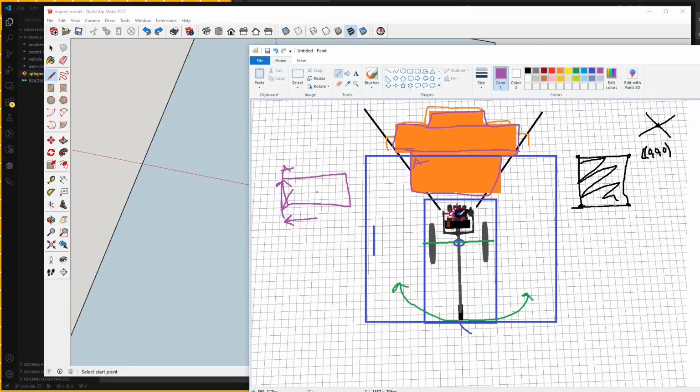And then with the IMU, if you say go forward 10 inches, which right now is assumed, there's no feedback yet with the IMU, but that will be added because I noticed even if I dial in the servos, it still slips somehow. So the 45 degrees is not perfect. But yeah, we'll start building a map from the scans, and so if it scans this, it'll move forward and scan again, and that'll be clear. That's the whole point of the robot, it'll keep exploring and building up this map and plotting